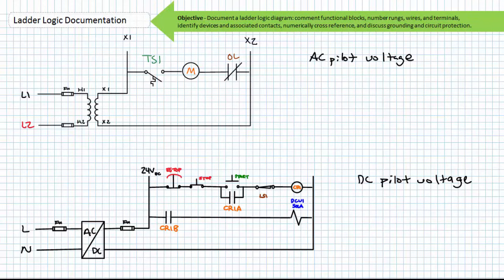Systems using ungrounded pilot voltage are sometimes referred to as floating. There is still a voltage differential between the left and right vertical upright, but since it's not referenced to ground, any voltage measurement employing ground as a reference is essentially meaningless. Any voltage measurement on pilot devices must therefore use 2 points with some electrical reference internal to the floating system. If, however, pilot voltage is to be grounded, it is customarily done so on the right-hand vertical upright. Now, any ground connection can be used as reference for a voltage measurement. Grounding one side of the ladder logic diagram serves other purposes, as we'll soon see.